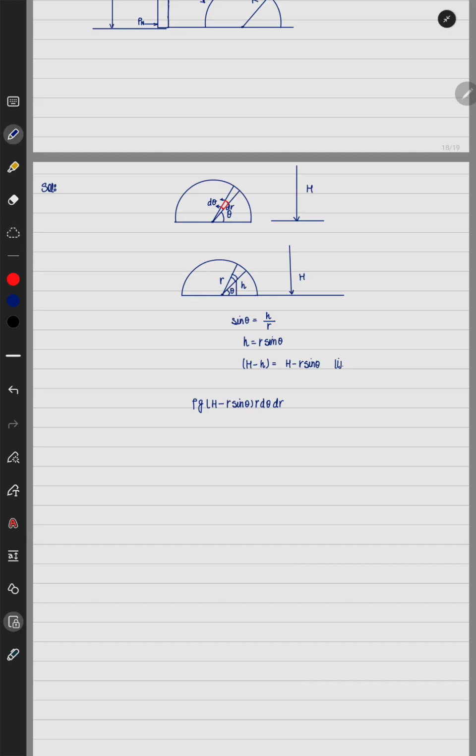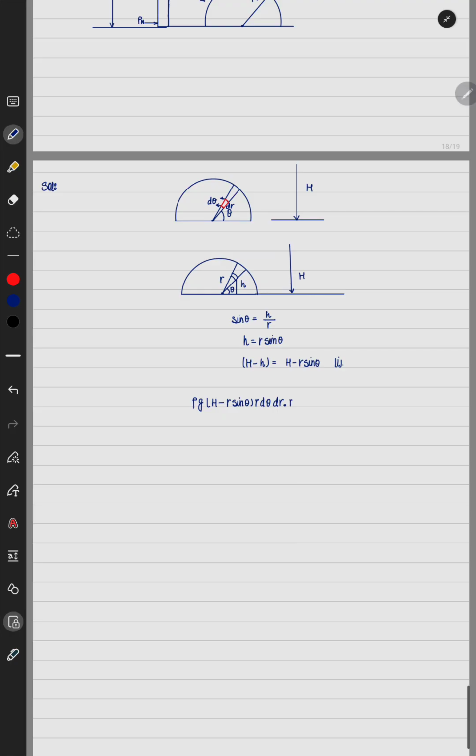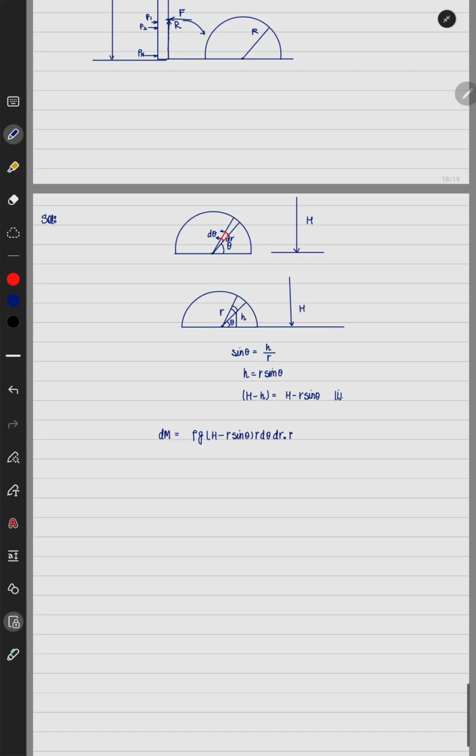So this is the total force, and multiplied with r, because r cross f. If I have to take r cross f, then the magnitude is given by r into f into sine theta, and sine theta is always equal to 1, so 1 need not be multiplied. So this gives me the total amount of torque associated with a very small element which we have taken.